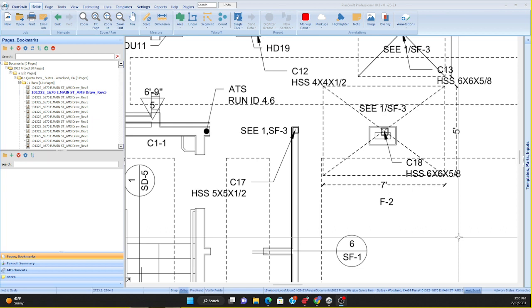A cost book will give you the cost of an assembly for the formwork, concrete, and reinforcement, if it's within a reasonable size. But normally the cost book will go up to 3 feet by 3 feet because industry standards, right, know already. If it's a 3 foot by 3 foot column base, typically there's already a set rebar size, five number fives or three number fives each way, whatever. Okay, so everything's industry standard, right?